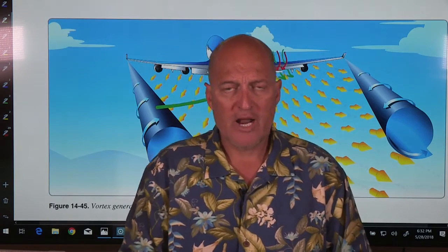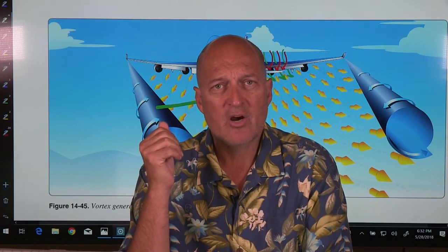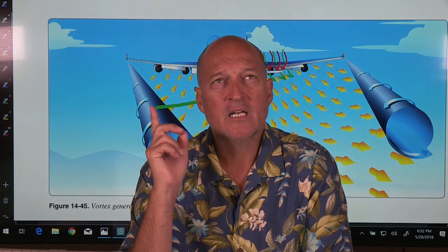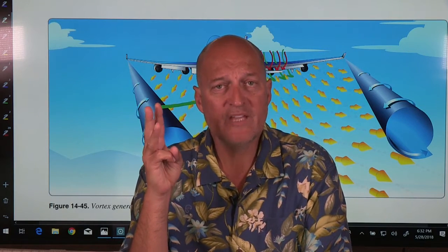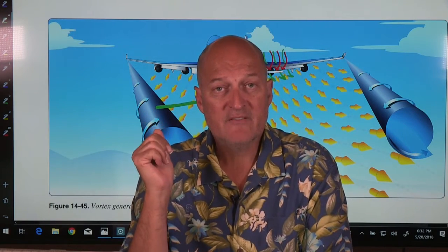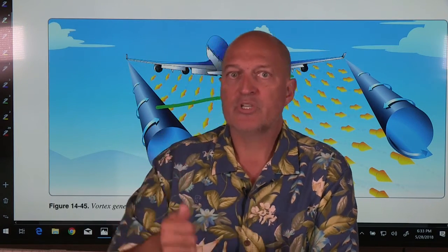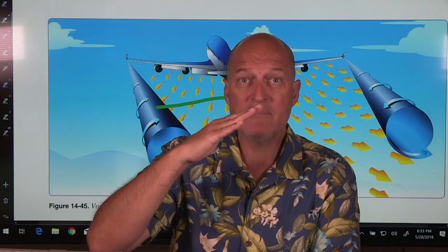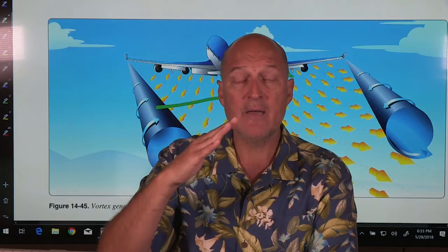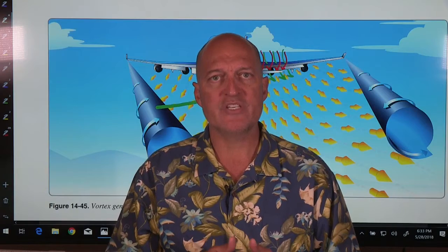Vortices for an aircraft are going to be greatest when that aircraft is clean, heavy, and slow. What does that mean? When would that configuration occur? That configuration occurs when you have a great big airplane that is taking off, has pulled up its gear, pulled up its flaps, and has a higher angle of attack. You've got a high power setting, high angle of attack because you're slower, you're starting to climb, and the airframe is clean. That's when the greatest vortices occur.